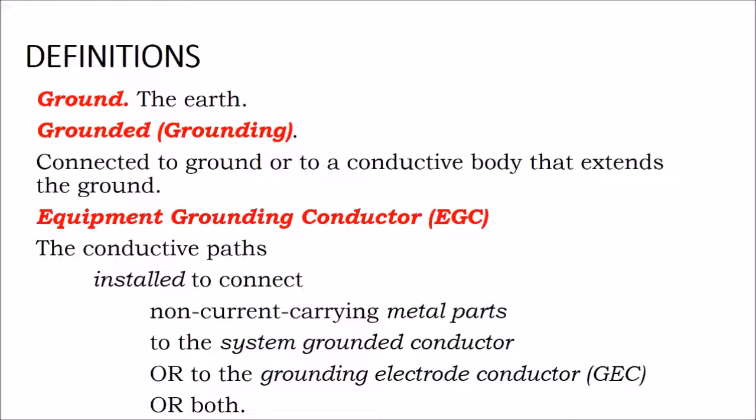So very quickly into sections 200 and 300, we're going to have these terms coming at us: the neutral wire, the grounded conductor, a ground plate, a ground rod. And it's important to understand what these are. And for now, just the equipment grounding conductor, the EGC.